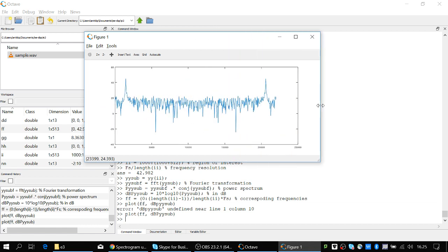Overlapping spectrum, actually, it's a repeating spectrum. So I don't need to plot all of it. What I need to do is just plot half of it. That's also okay, and it is correct, except that the second half is basically the negative frequencies, because these frequencies are the same as the negative frequencies.